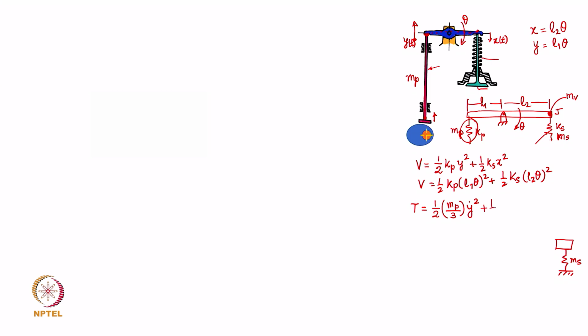Okay. Now, what else you have next in the line? The rocker arm. So, that is a rigid rocker arm and therefore, the kinetic energy of the rocker arm is half J theta dot square, that is the kinetic energy of the rocker arm, followed by what do you have here at the other end of the rocker arm on the right hand side, you have a valve which is getting pushed. Okay, that valve is not getting compressed, so it is assumed rigid.